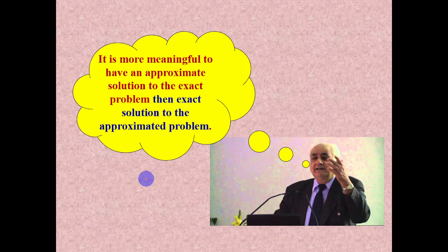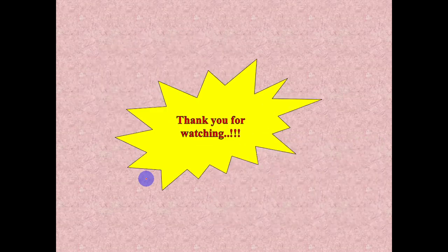Even if you are working to ten digits after the decimal in analysis and design, that is a waste. Suppose instead of a fixed support you consider a pinned support, all our analysis will go wrong. That is very important once you start working on live projects. What we have seen is a brief introduction to analysis. The analysis itself depends on the excitation of loading, whether it is static or dynamic, so we must decide when to go for static analysis and when for dynamic analysis.